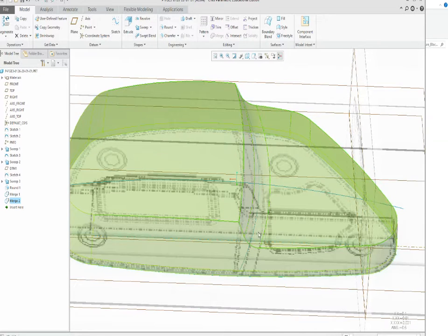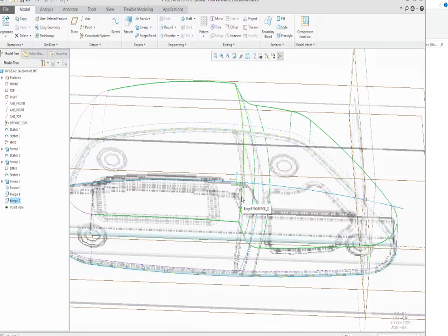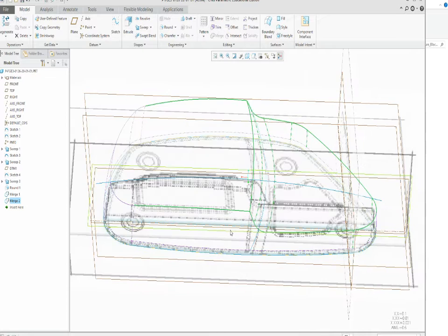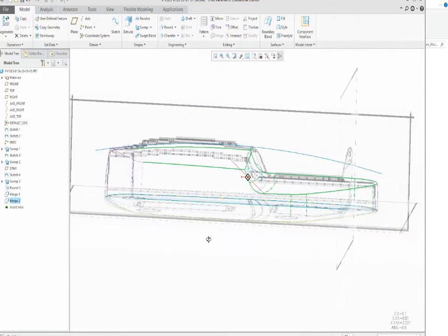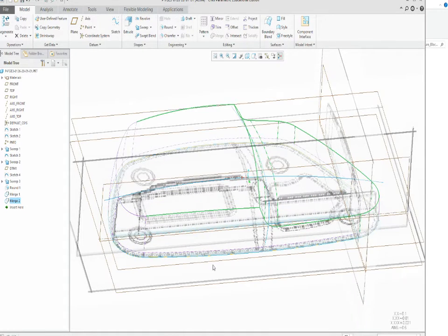So if we look at this, a large fillet here, when it gets offset in, is going to have a tendency to get bigger. If we have a small fillet here and it gets offset in, it's going to go to nothing. So those are some of the challenges that you can run into on your designs. You just got to watch it and make sure it's machinable on the design.